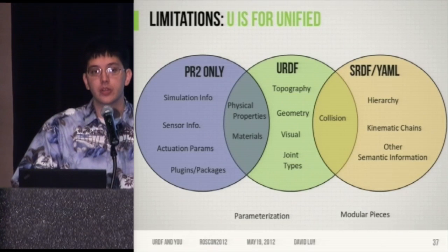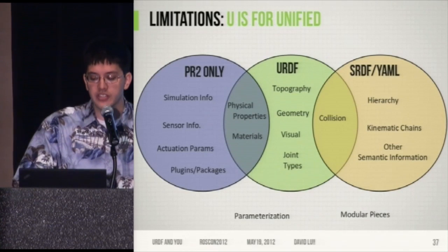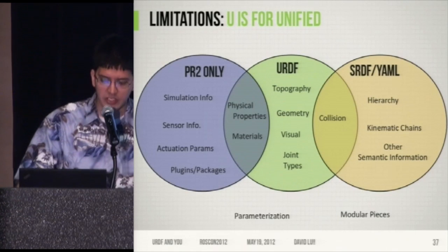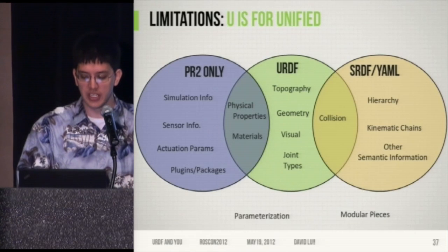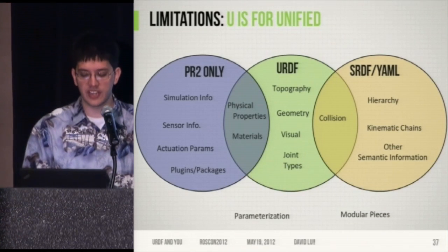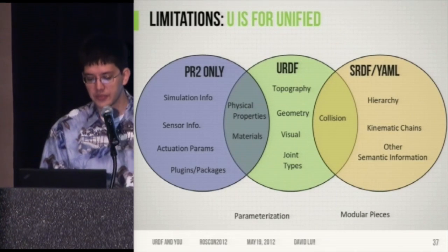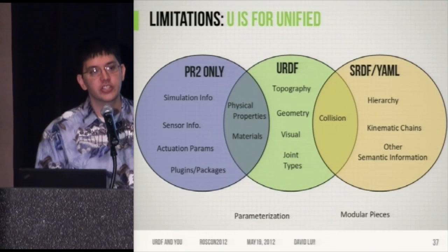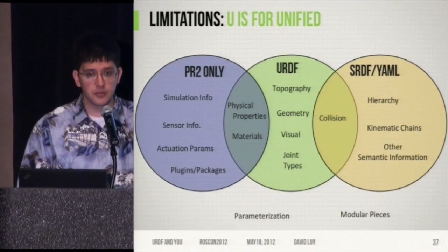And then there's also a bit of collision information that's either specified in YAML or SRDF. And so that's what elements should you check to see whether or not they collide. That information's in the SRDF or config files, whereas the actual collision geometries are defined in the URDF. And then there's other information like the parameterization that is only specified in the Xacro files.